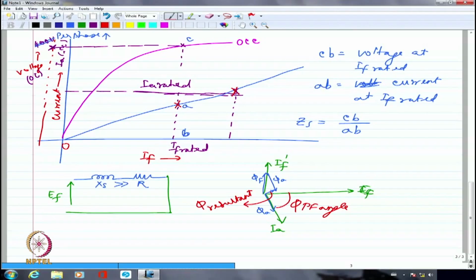Absolutely. We would have gone way beyond saturation. A very, very huge amount of flux. If the saturation had not been there, you would have seen a huge amount of flux. That's one reason why whenever you connect a capacitive load in a synchronous generator, again, we talked about this in transformer. When we connected capacitive load, we had negative voltage regulation. Right? At no load, if you had 230 volts, at full load capacitive, you would have 240, 250, 260 volts,